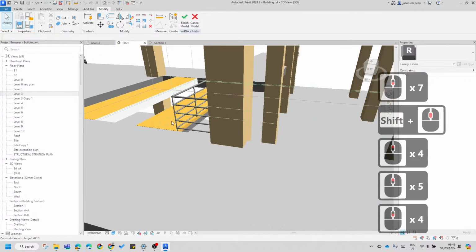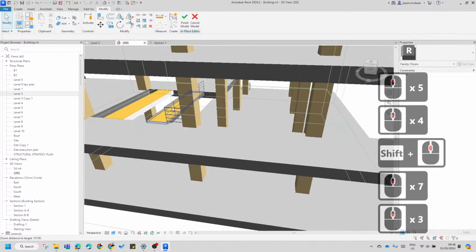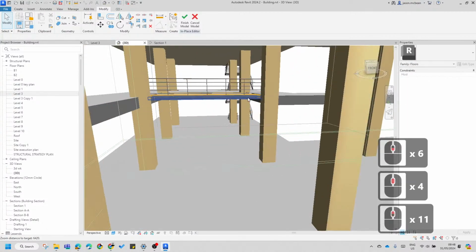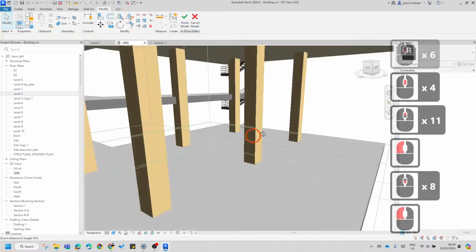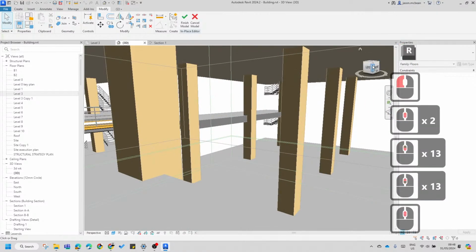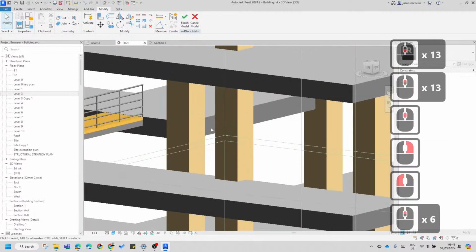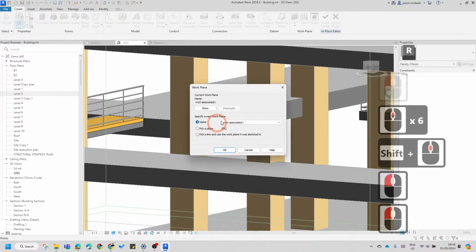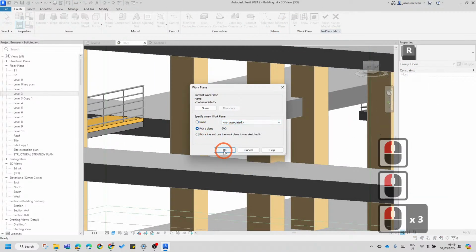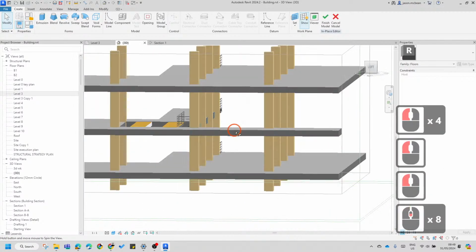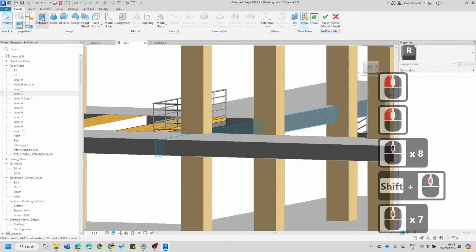If you're going to use in-place, in the in-place family, say I want to make a new bridge somewhere else. Now these are dependent on work planes. So here in this view, and remember it'll put in the right category. This changes to orthographic. Okay, I should change the section box. But now if I go and say create, set work plane, I'm going to say pick plane, and I'm going to pick this face here. Now I can create the same things. Extrusion.